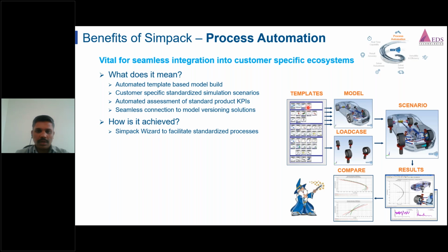So from these predefined models, we can directly build this full vehicle. Also, there are predefined load cases, so we can select the load case. We can combine these two, model and load case, so we will get here one scenario, for example handling or something else you have taken. So you will get the scenario, and then you can directly run that, and you will get the results. This will deliver the standardized results, and you can also automatically compare those standardized results.